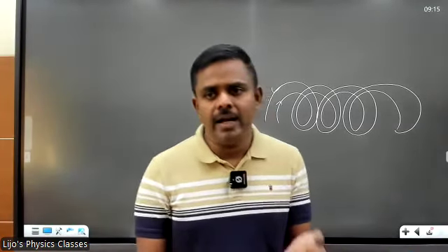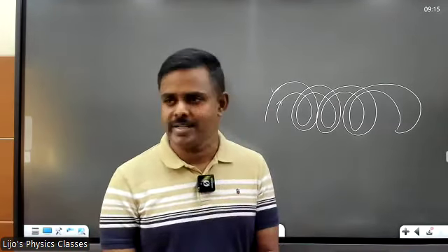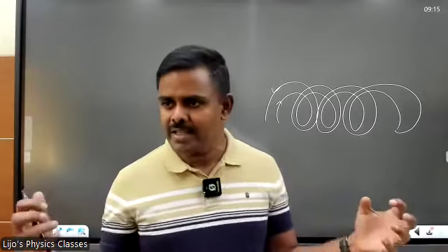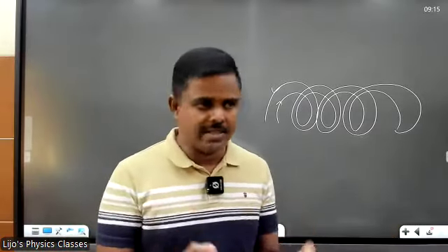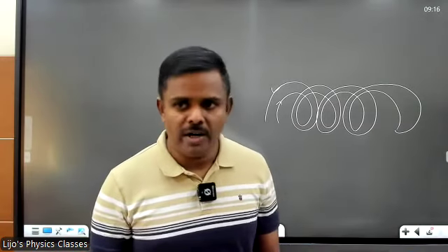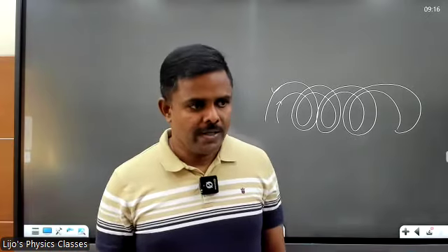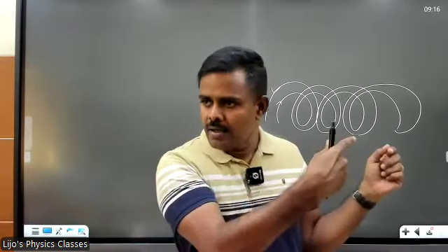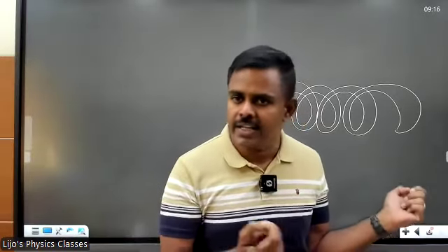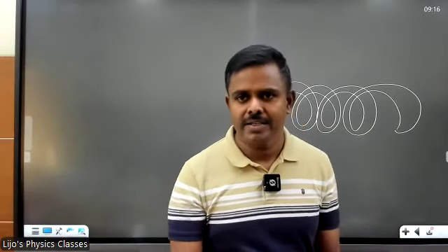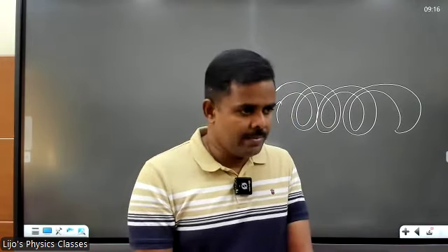In standard laboratory resistance boxes, if you open the back side, you can see the coils. The coils provide the resistance. But what I want is pure resistance, right? What is the problem? When you wind it in a coil, it always gives induction, electromagnetic induction. Correct? Induction effects are not needed at all. You don't need them. Got it?